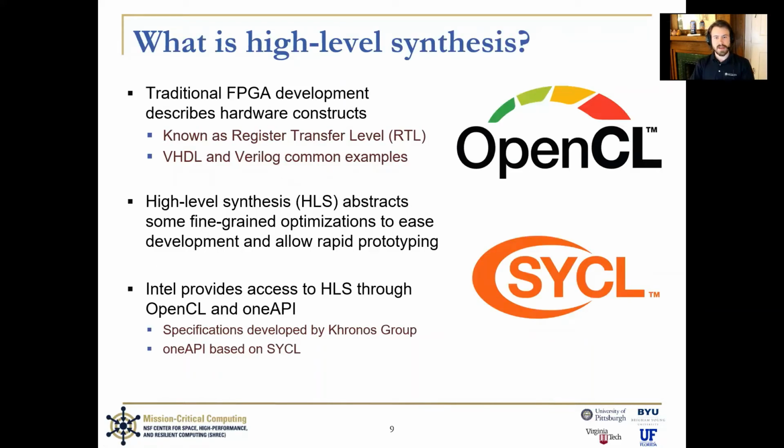Now we can take a look at high-level synthesis. So we know traditional FPGA development is used to describe hardware constructs and often uses fine-tuned optimizations to make things work as efficiently as possible. This is known as register transfer level, or RTL programming. VHDL and Verilog are common examples.